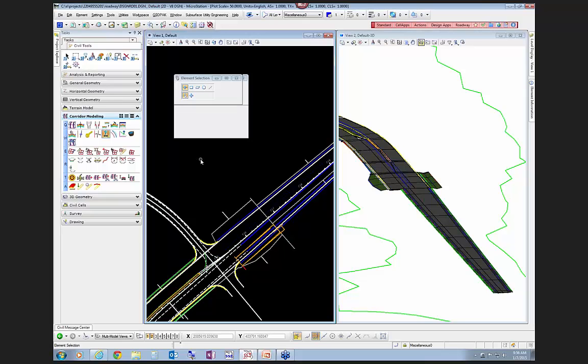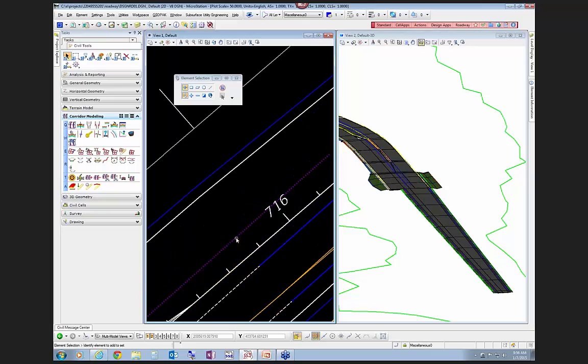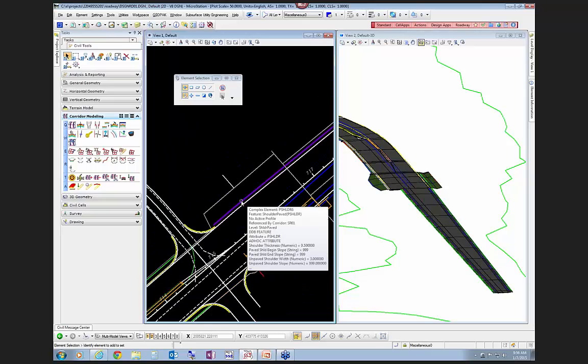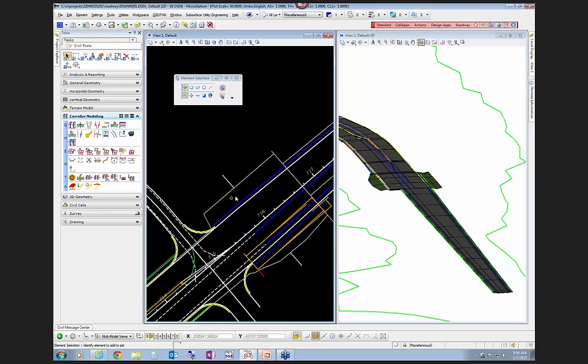The other thing is, if you have trigger lines, then trigger lines need to have lines or things that turn them on and off. When you have switches, it doesn't matter. You can just turn on and off things as you will, based on the number and the actual parametric constraint station range. Because if you look at the parametric constraints, well, I can't look at it here, but let's see if I look at the corridor objects on here and look at the parametric constraints.